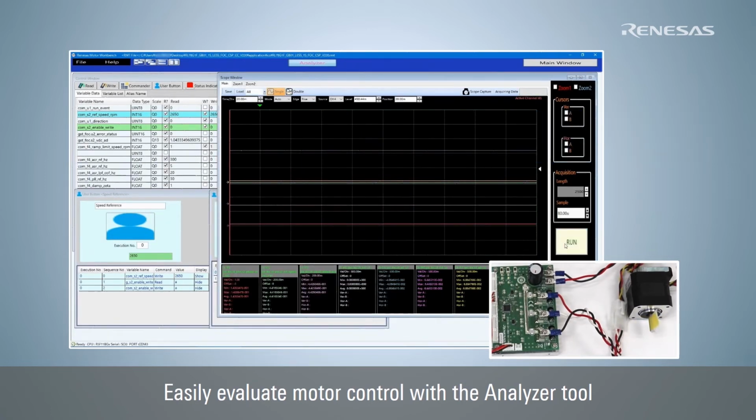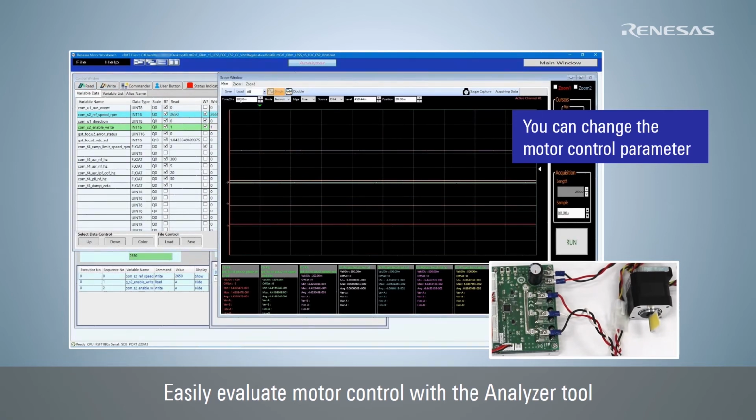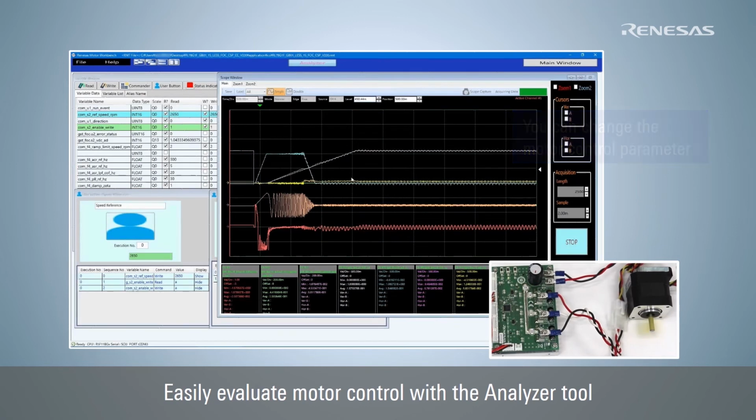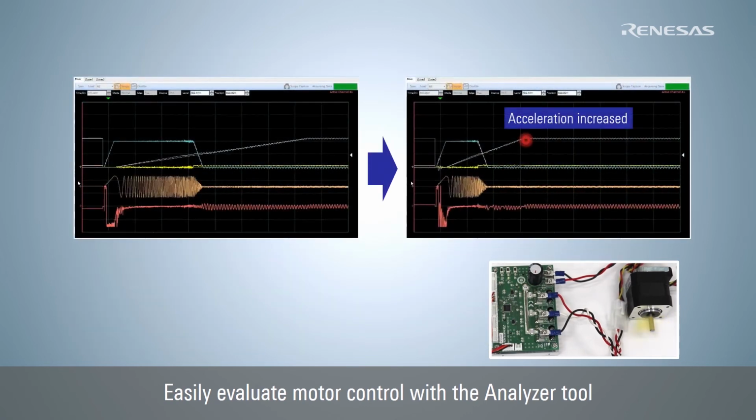Now change the parameters and check that the starting waveform of the motor changes. If you increase the value of the acceleration variable in the control window and drive the motor in the starting waveform acquisition state, the initial setting of the scope window, you will see from the displayed starting waveform that the acceleration has become larger than before. In this way, you can quickly evaluate the motor driving by rewriting the variables inside the microcontroller.